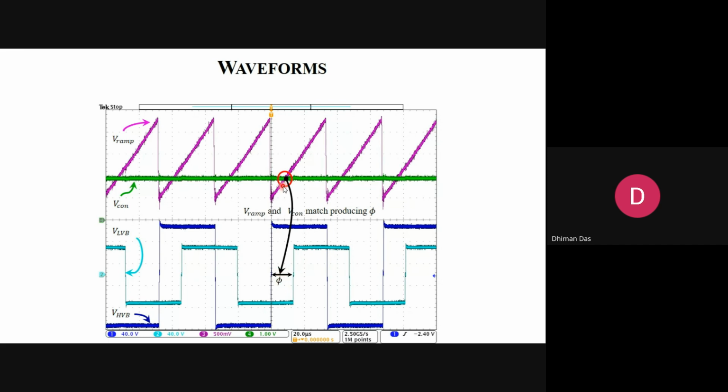When you do so, you know the phase and amplitude of this perturbation. Now you can collect the output current, and you can analyze what phase difference and amplitude deviation happen between the steady state and the perturbed state.